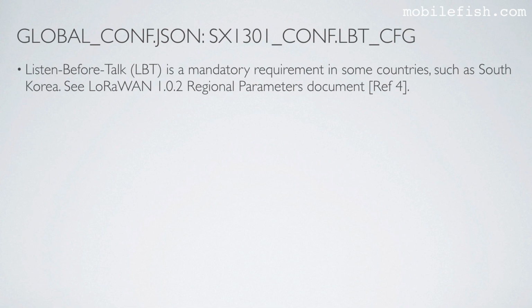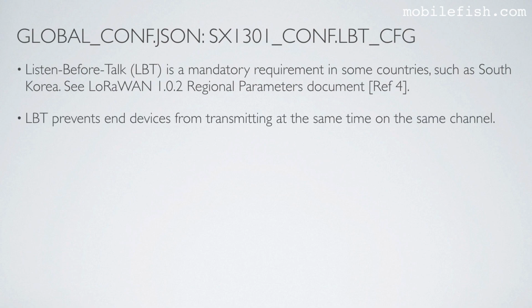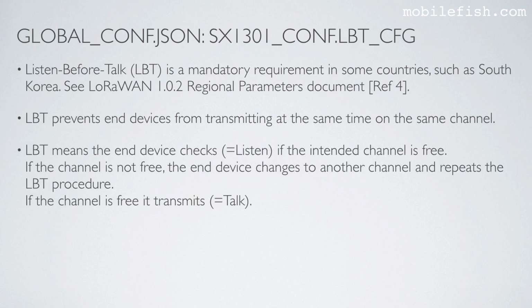Listen before talk, or LBT, is a mandatory requirement in some countries, such as South Korea. See LoRaWAN 1.0.2 Regional Parameters document. LBT prevents end devices from transmitting at the same time on the same channel. LBT means the end device checks, meaning listen, if the intended channel is free. If the channel is not free, the end device changes to another channel and repeats the LBT procedure. If the channel is free, it transmits, meaning talk.